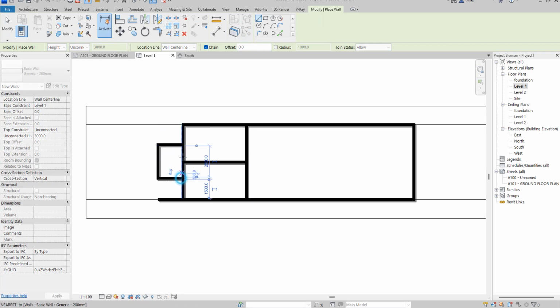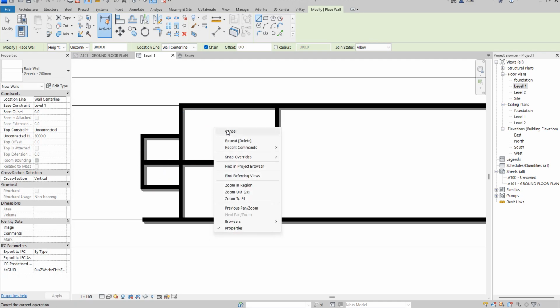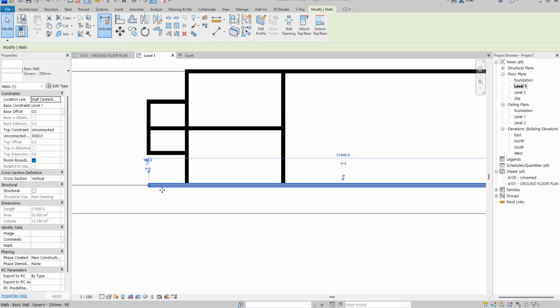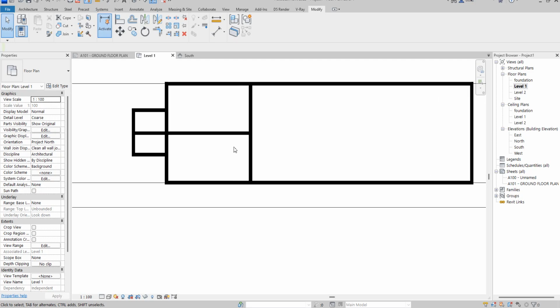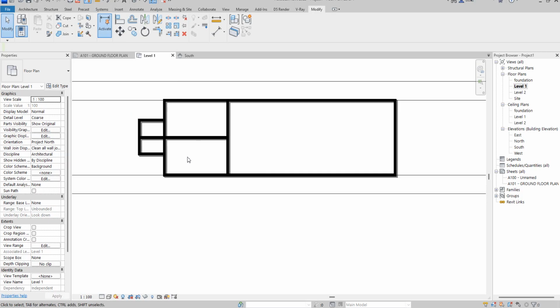So what would this one be for? This one is going to serve as the toilets for this room, because when you are creating a room, you must look at cross ventilation. So there should be no ventilation issue. When you are not designing a terrace, you must know that all your rooms that you are creating, if not all, then most, must be cross ventilated for good air breathing for the occupants.